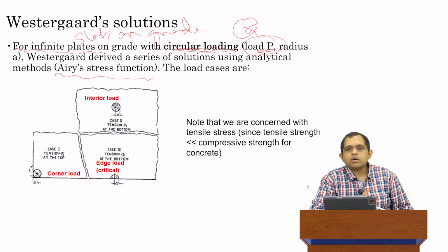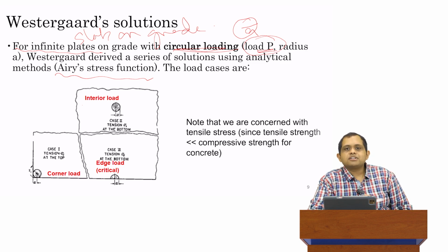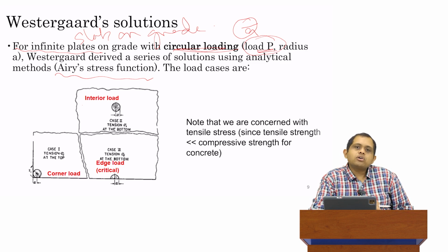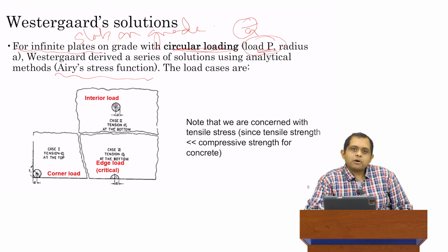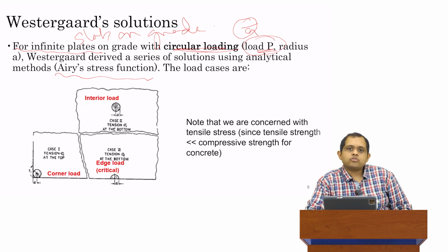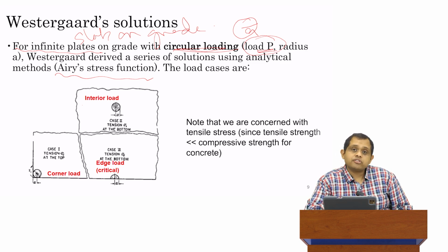Each of the solutions is going to satisfy some boundary conditions. So they satisfy, of course, the biharmonic equation, and they satisfy certain boundary conditions. And then you look back and you think, okay, my problem has these boundary conditions. Which of these solutions that mathematicians have come up with satisfy these boundary conditions? I find the best solution which satisfies the biharmonic equation but also satisfies the boundary conditions which represent my problem. Combine those two together, and that's how you get the solution for your problem.